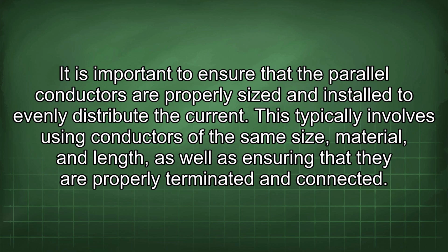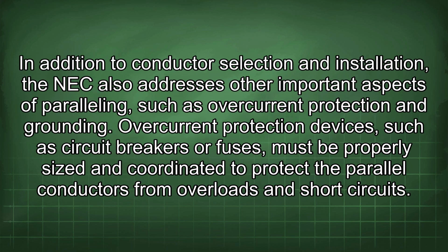It is important to ensure that the parallel conductors are properly sized and installed to evenly distribute the current. This typically involves using conductors of the same size, material, and length, as well as ensuring that they are properly terminated and connected.